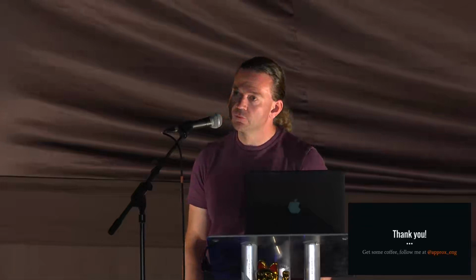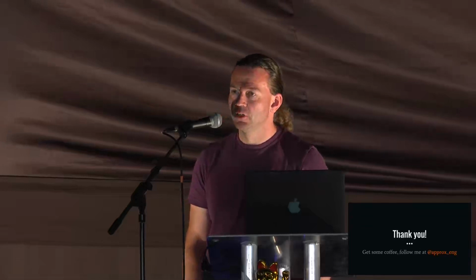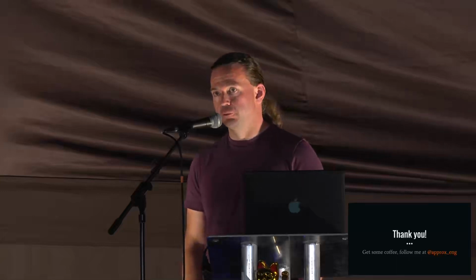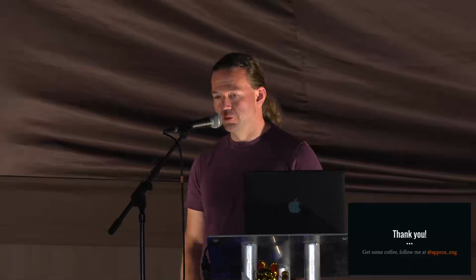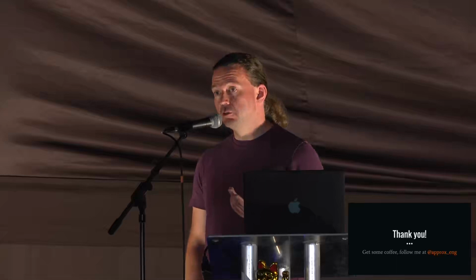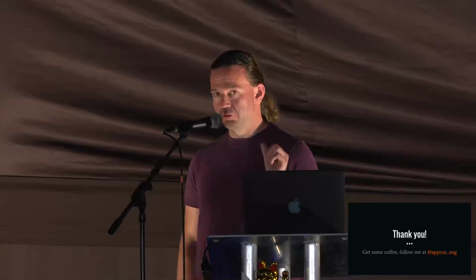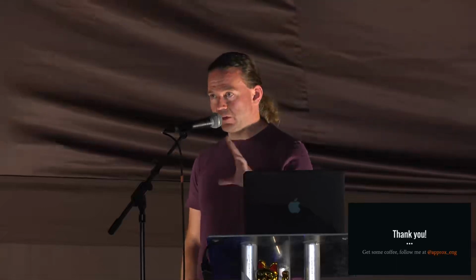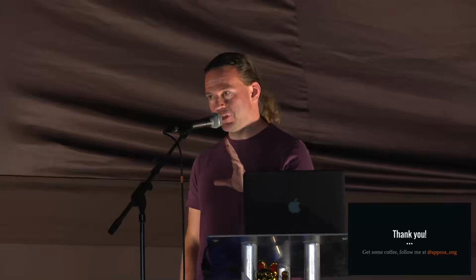I think you made a statement earlier that you said drones couldn't be holonomic. Is that all drones, or? So the reason I said that is that if you consider three-dimensional movement, you suddenly have a very large number of degrees of freedom. So you've got translation up and down, left, right, forward, back. You've also got rotation around each of three axes. And I think you'll find if you have a quadcopter that if you turn it so that it's banking left, it will move sideways. It's very difficult. You could, in principle, create a drone that could behave in a holonomic way, but no one ever would.